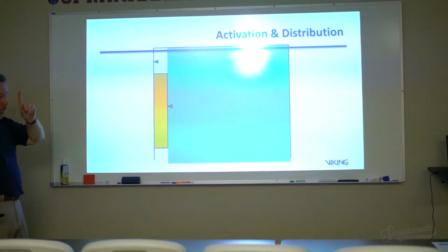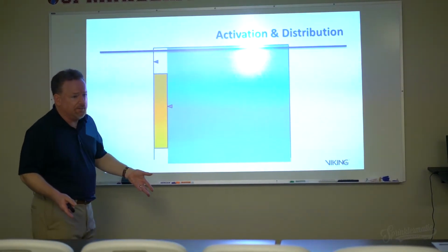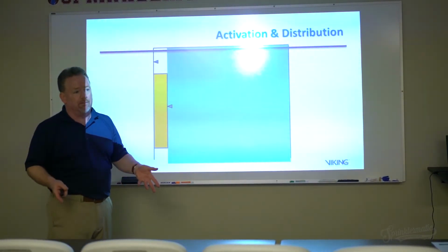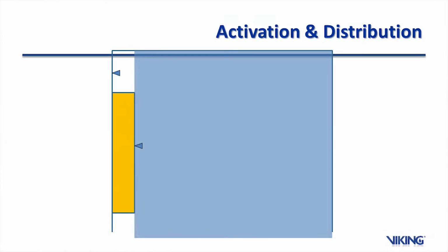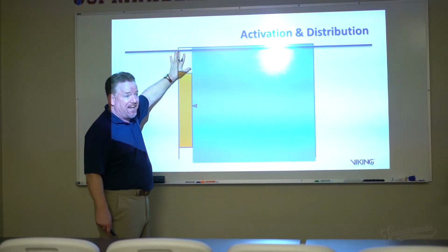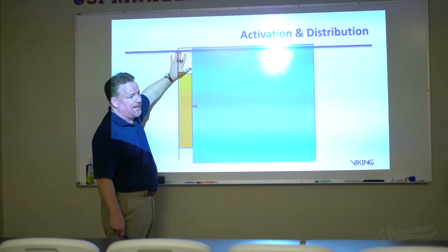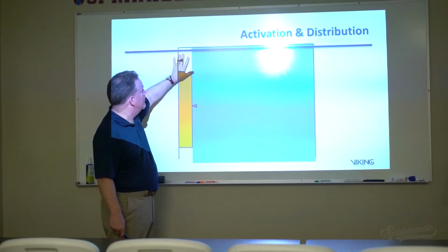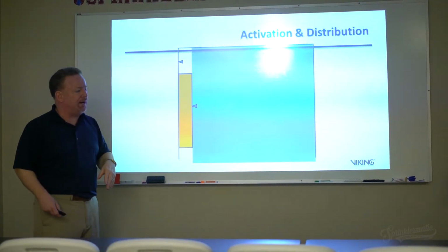The other thing is that nowhere in the standard did it say that you have to get 0.1 or the density over the entire area that it's required. It never really said anything about little shadow areas like this. In fact, we've had obstruction rules in the standard for decades, understanding that in some cases you have obstructions to the spray pattern that might affect the spray pattern getting to a particular spot.